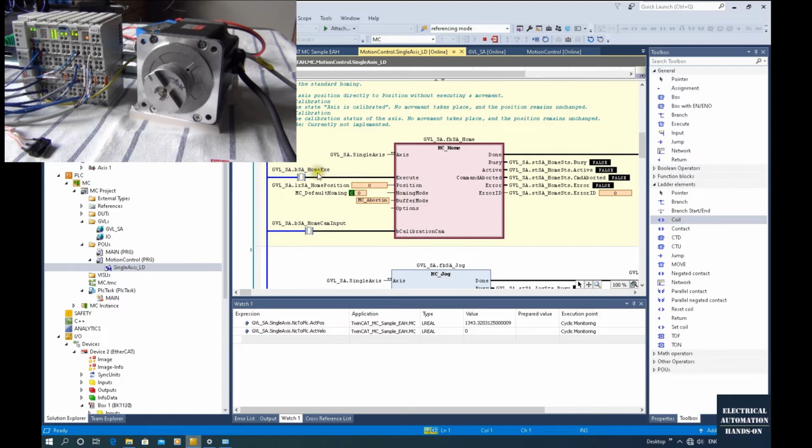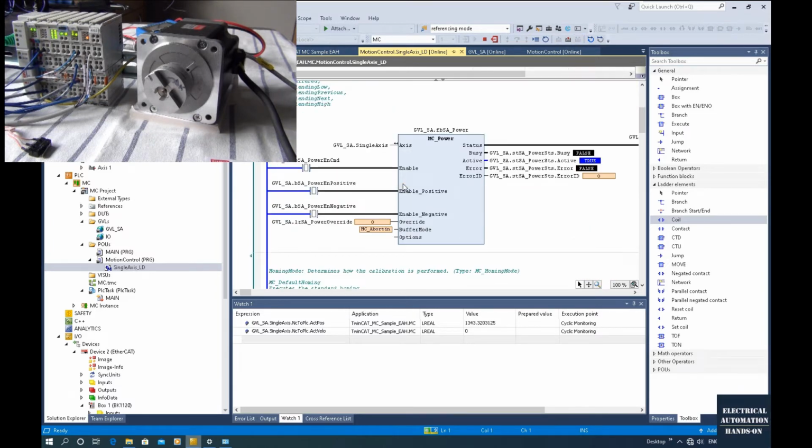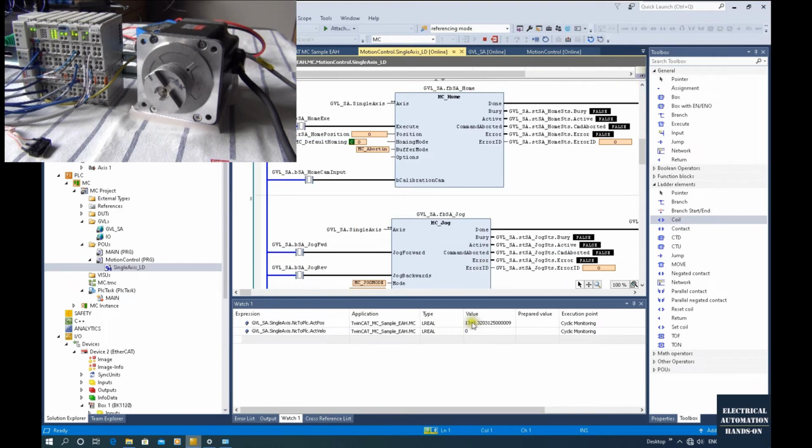Okay, before we trigger that, we make sure our motor, let's reset everything. Reset the fault. This is basically the start procedure after we shut down the power, after we cycle power on the machine, right? So after we reset everything, make sure there's no fault from the motion, and then we power on the motion and override speed. Okay, so we enable the motion first, and at that time the value doesn't make sense. Maybe your tooling or your pallet motion system is stopped at someplace else. And now we will execute this home sequence.